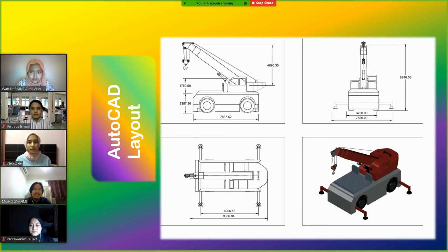If we are comparing the trapezoidal cross-section hook with the circular cross-section hook type, the trapezoidal cross-section type is much better, in which the stresses induced through it are much lower compared to the circular cross-section, because it is able to absorb more vertical load and deflection. Besides, it can absorb and store more strain energy, thereby ensuring safety of the crane.